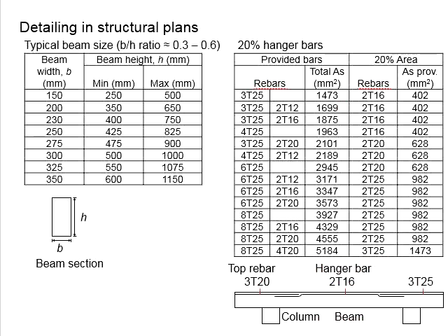You do not want this to happen. You do not want the hanger bar to be unable to effectively disperse the stress to the nearby elements of the member, in which case you need to increase the amount of reinforcement bar slightly to ensure it is more than 20% of the large amount of reinforcement bar at the adjacent support. This is the idea of the 20% hanger bars.